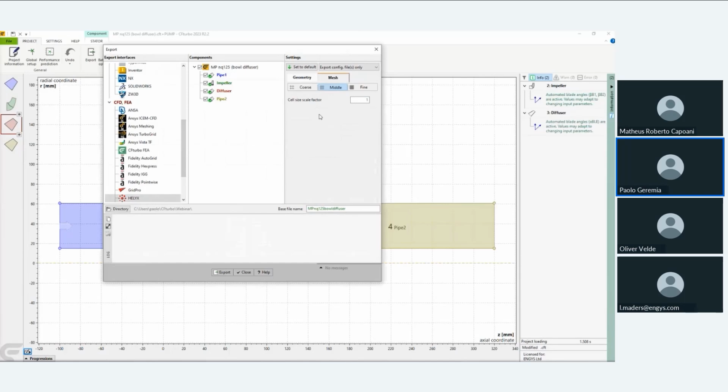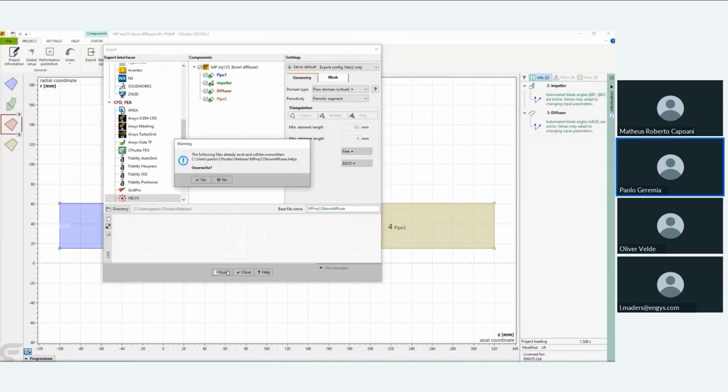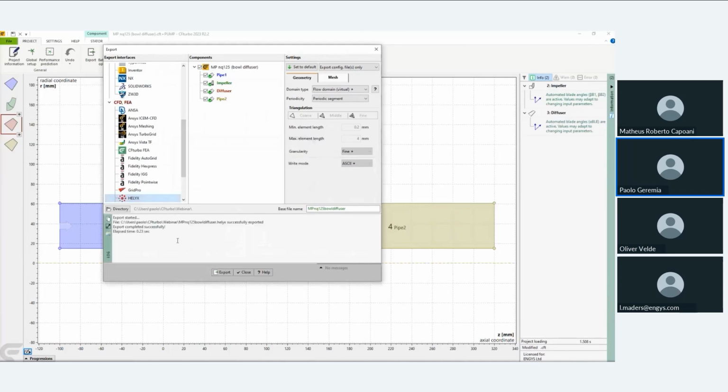In terms of settings, we just use the default settings for the geometry, and the same applies to the mesh. So we just use the default scale factor. Scale factor is a scalar parameter which allows you to scale the cell size of the background mesh accordingly. If you make this number higher, we will have a resulting mesh with a coarser cell size.